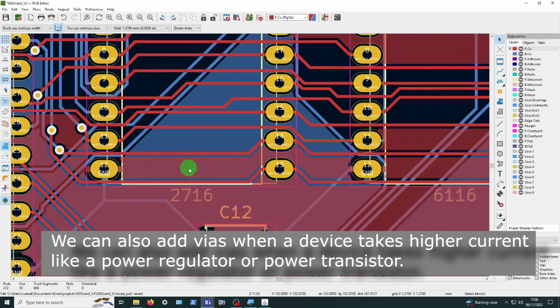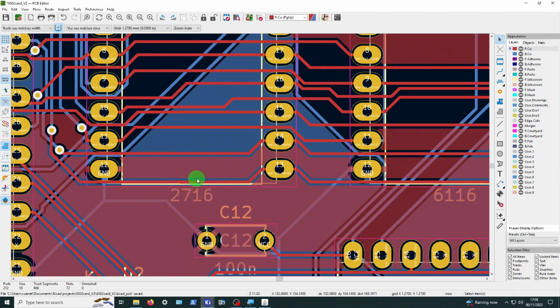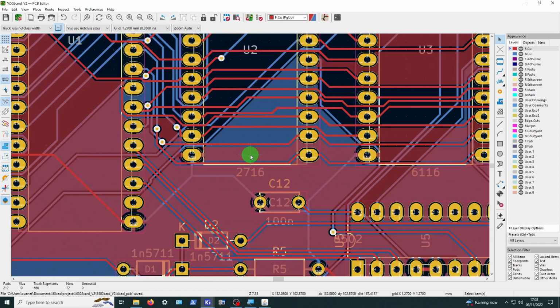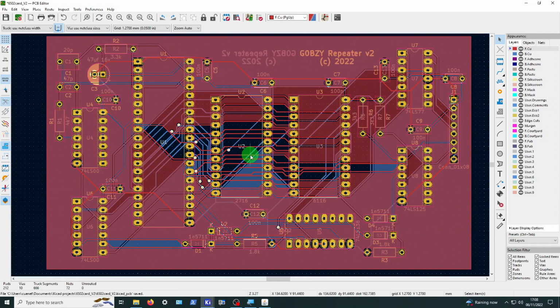But you would know if there was a problem, because the design rule checker would tell you that that pin is not connected to ground. So all you've got to do is put in the vias to connect this blue area, which is the bottom copper, to the top copper, and that usually sorts it out, as long as you've got earth underneath there. So you really have to go in and be careful and make sure everything is connected. Rely on the design rule checker, trust it to be accurate, and follow what it says. And if there's something not connected, then go in and sort it out.